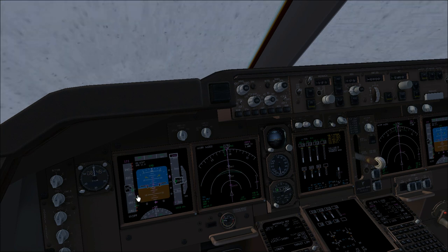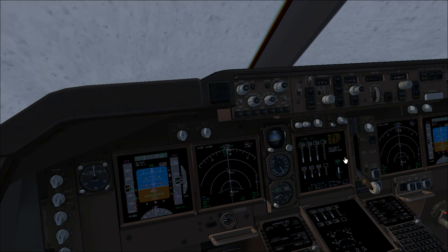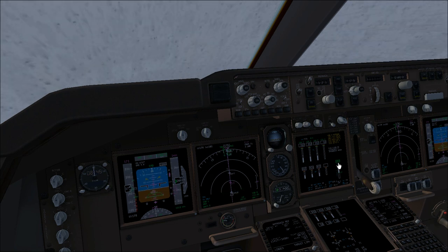The flaps are, as you can see, the yellow is the caution range. Anyway, we are now selecting the flap stand, and we are just going down to the right speed. If we're speeding down, we can set the gear down to speed up the deceleration, and we are now completely on the lock, waiting for 2500. Gear is now green light, and we can now select flaps 20 and the speed for flaps 20.